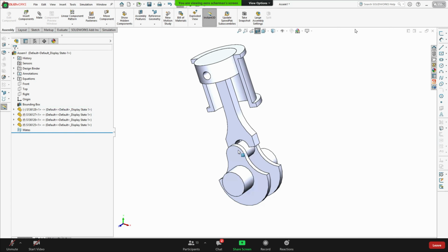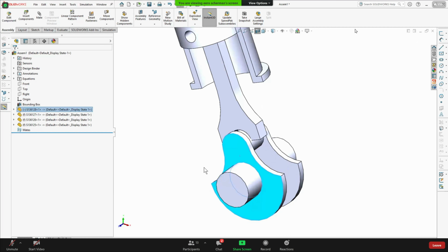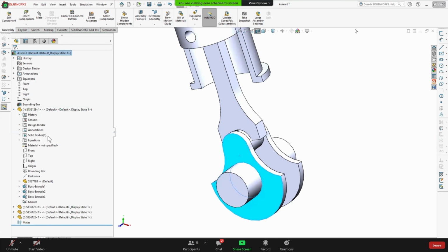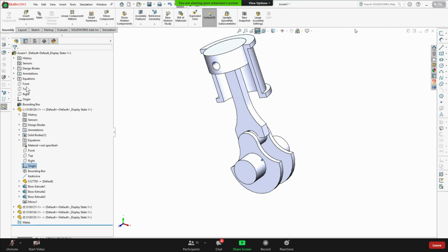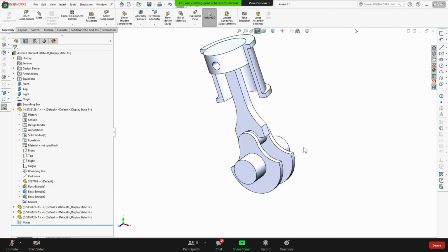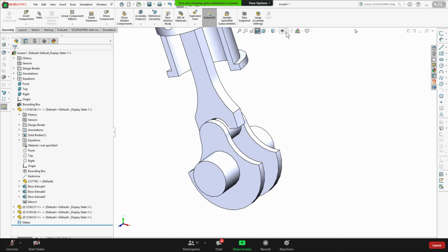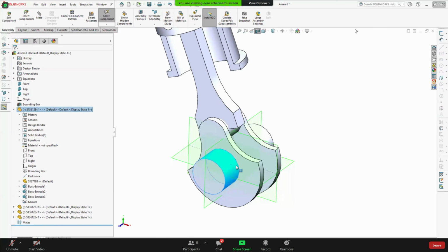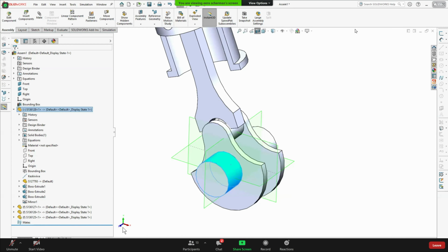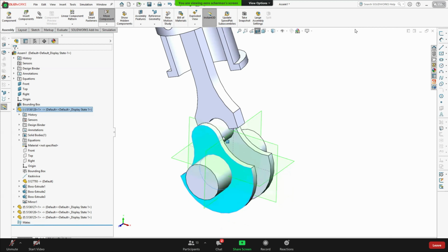So one way to make the part rotate is to think that, okay, I have an origin in the part, and I have 3 planes in my assembly. Can someone say, if I make the planes visible, how could I make the crankshaft rotate around the z-axis, but maintain the position of the crankshaft defined?